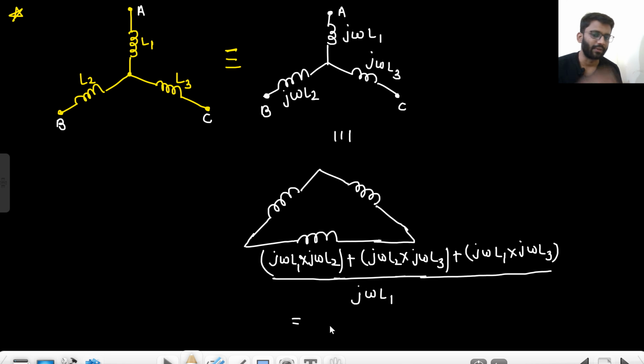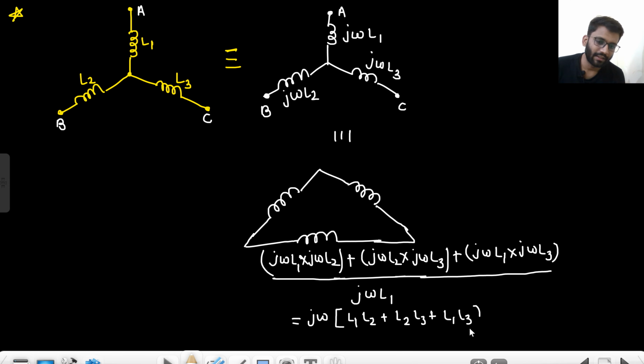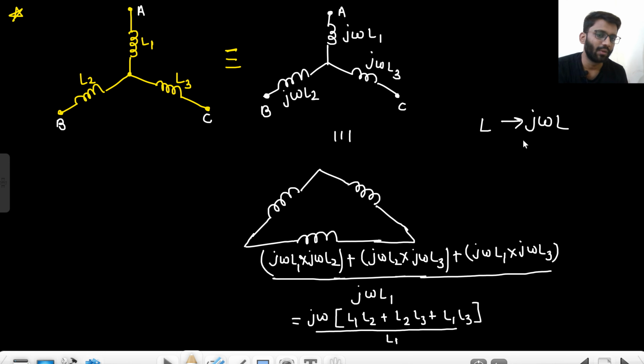So what is the final result that you get? j omega to j omega get cancelled and one j omega is outside. So it is L1 L2 plus L2 L3 plus L1 L3 divided by L1. Because from here we got j omega square, and j omega square to j omega got cancelled. So only j omega is left. So basically if you have an inductance of L, it provides an impedance of j omega L. Or if you have an impedance of j omega L, it provides an inductance of L.